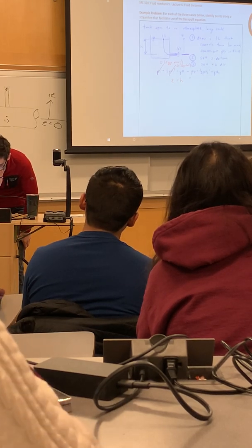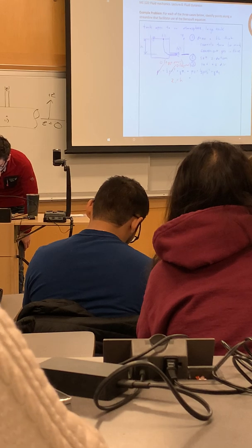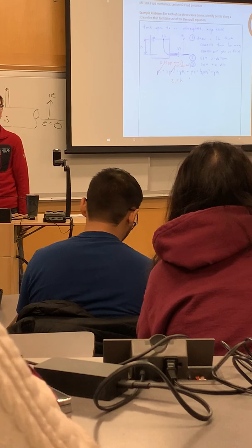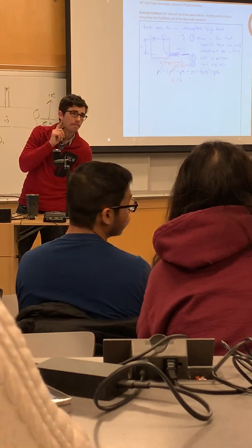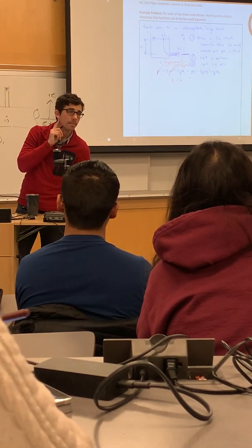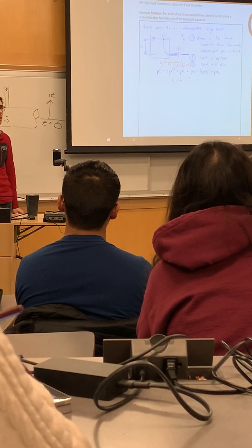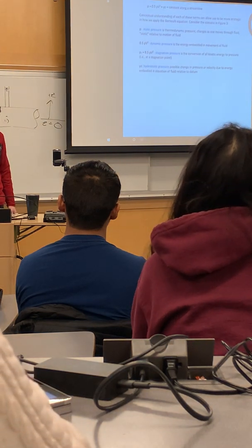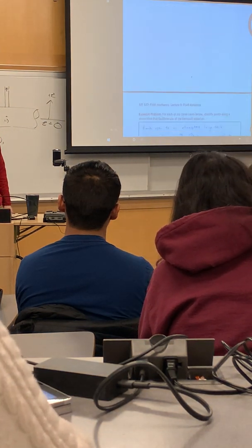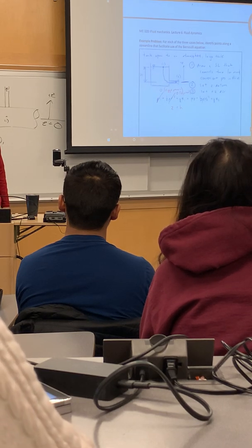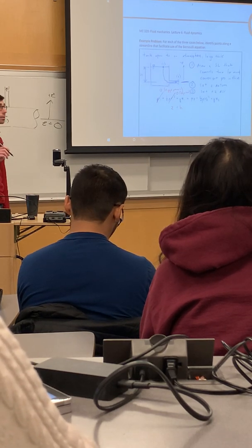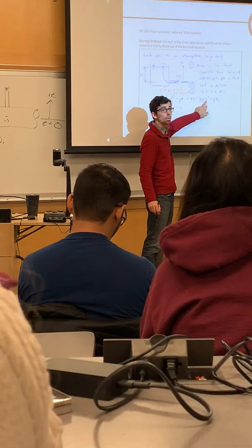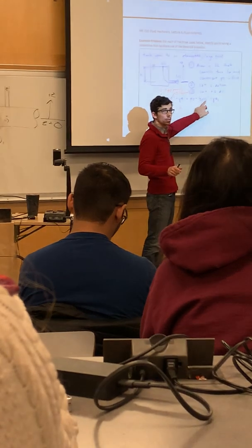So what about here on the right-hand side? What can we simplify? Would you call the P2 like a dynamic pressure or something? Would you call pressure at point 2 like a dynamic pressure from our previous page? The dynamic pressure is 0.5 rho v squared. P2 is the static pressure at point 2, right? So the dynamic pressure is this term right here. Okay. So the dynamic pressure is non-zero.